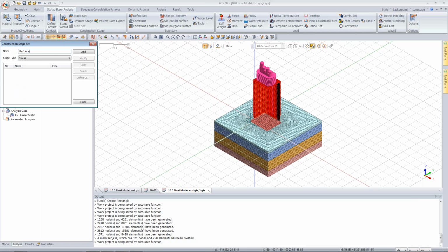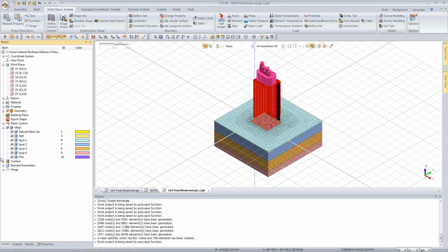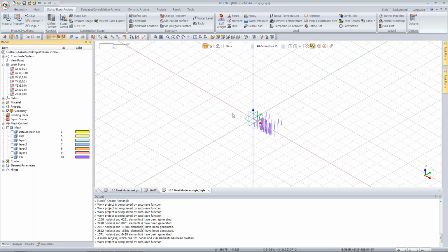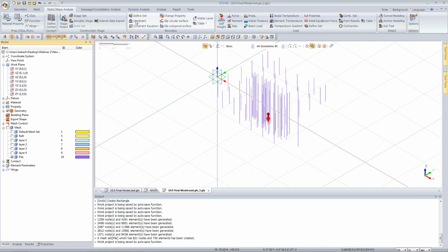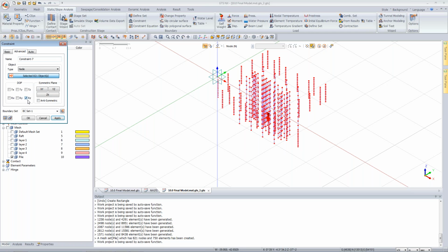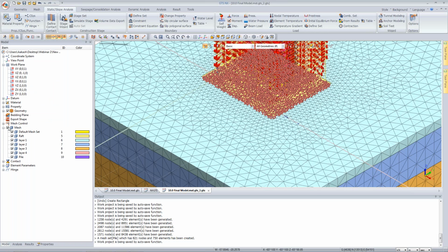So in this case, I'm sorry, I forgot boundary conditions. Now for the piles, if I go to model, I just hide. So one more boundary condition. We have to restrain the piles for RZ. So you come to constraint, you go to advance, select all, and RZ for the rotation in Z direction, and you can give it a name, pile constraint. Okay. So three boundary conditions: one for the support conditions, second the change property, and third the pile restraint. I'm sorry for that.